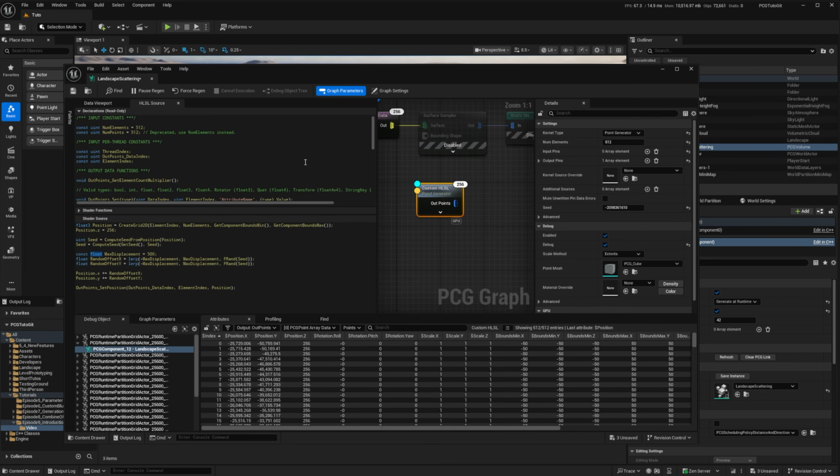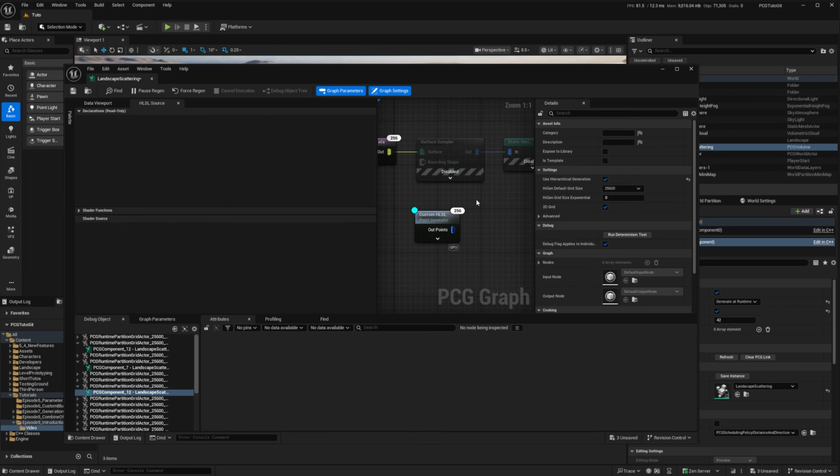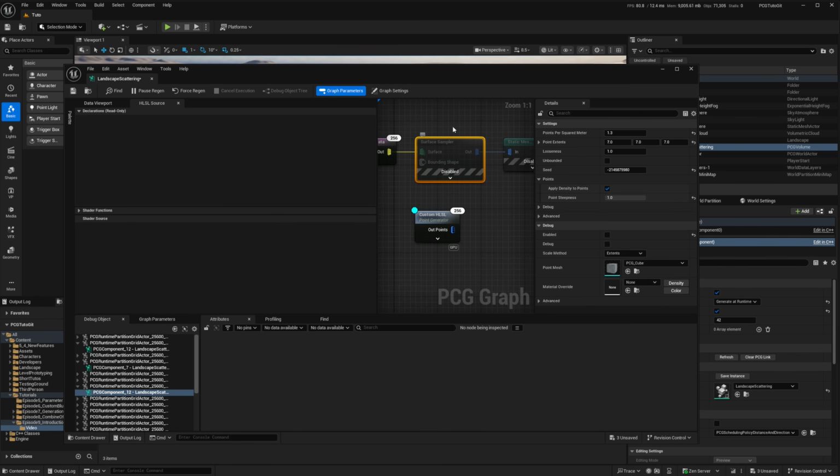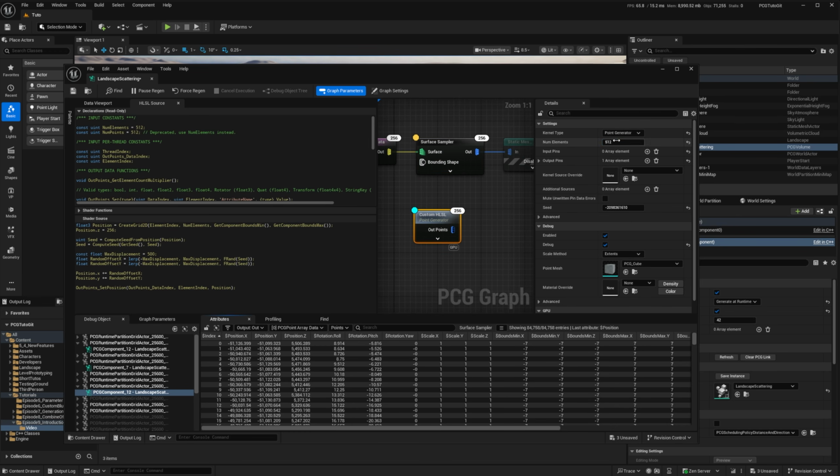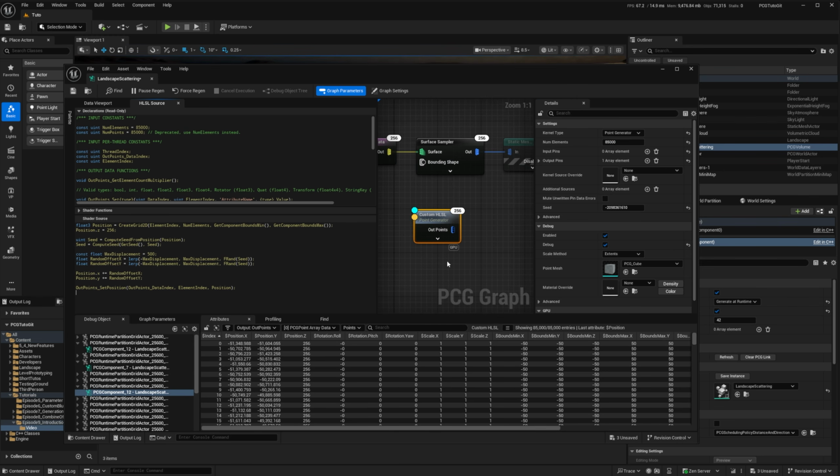It's very important. Talking about the surface sampler, let's see how many points are generated in our setup. Close to 85k, and the points extent is 7. So let's crank our numbers to 85k and set the bounds to -7 and +7.